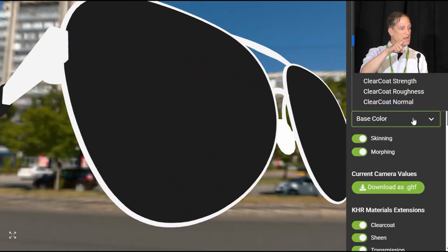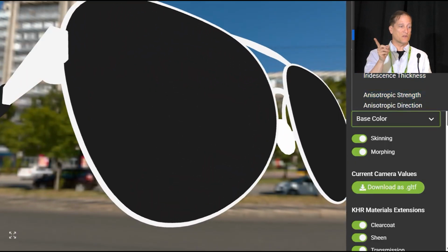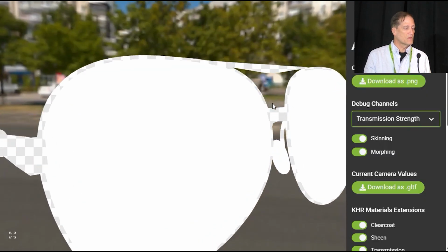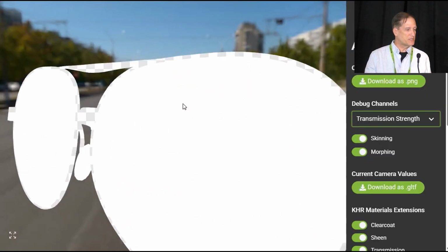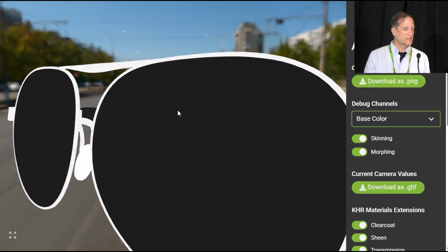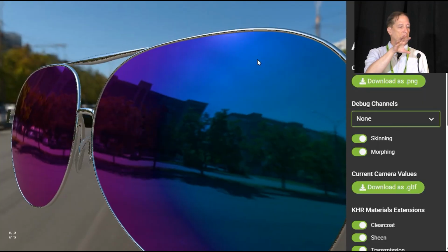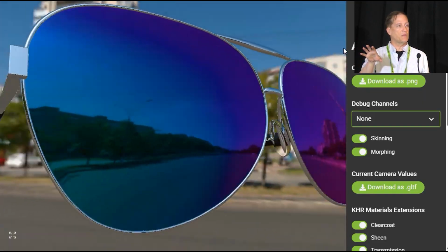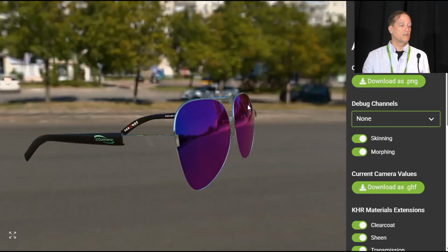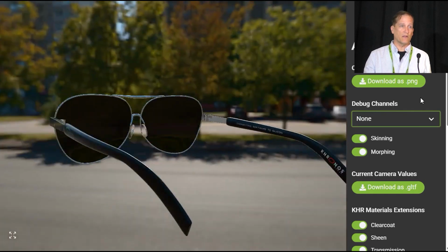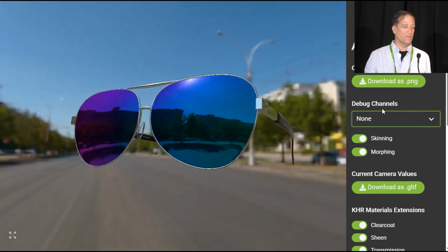And so all of the light bending happens in the bevels of the surface. It has full transmission, so that's only on the glass. And what else? The base color. So the darker that the base color is, the less transmissive it is in PBR, in glTF PBR. So the darker that you make the base color, the less light is going to come through.